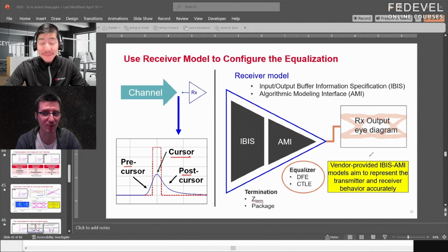So when you do these very high speed signals, maybe the problem is not in hardware but in the settings. Oh yeah, for sure. And the newest PCIe 7 standard has, let me think, 7 different CTLE presets, 11 FFE presets.